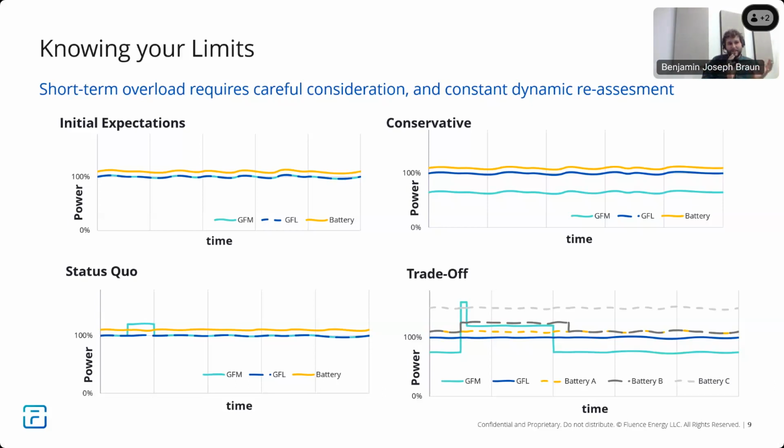So these types of grid forming aspects, whether it's more voltage stability related with the short circuit level, or frequency stability related with inertia and angle jump power, these are very, very transient things, and you can either size them with a blunt steady state manner, or you can try to be a little bit more complex and follow this trade-off down at the bottom right.